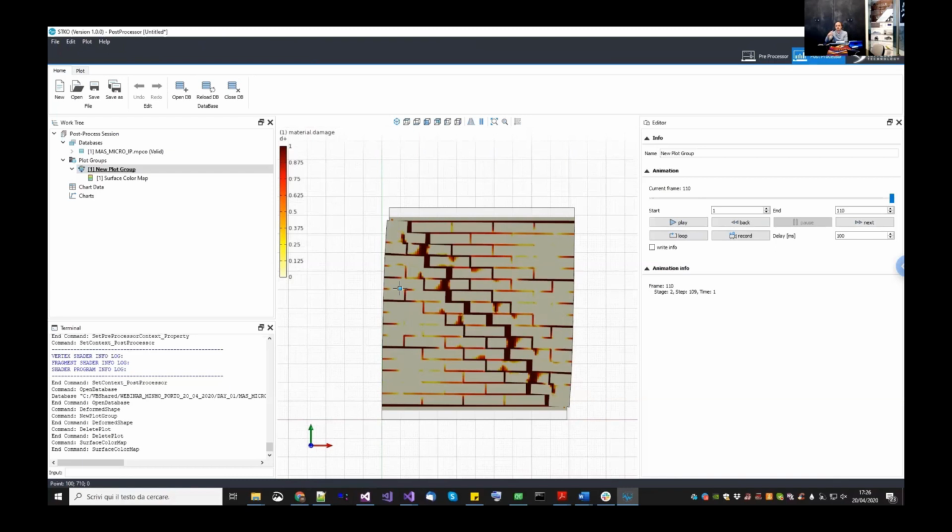And then I will show you how to use a new material model that we put in OpenSees, which is called Orthotropic Mapper, which is basically a wrapper that takes any nonlinear isotropic model, and with few material parameters, it can change that model into an orthotropic one, and it works with any nonlinear model. So in this case, we apply it to our tension compression damage model, but it can be applied, for example, to the J2 plasticity to obtain the Hill plasticity for orthotropic steel. It is the same.